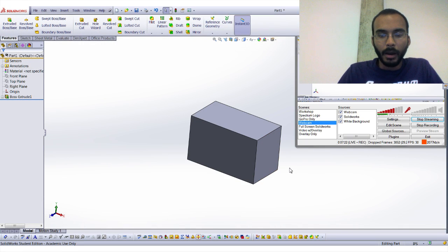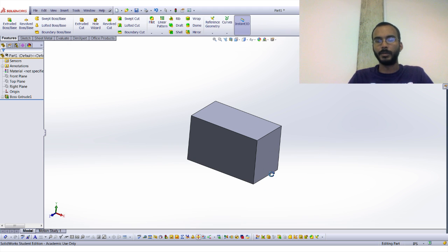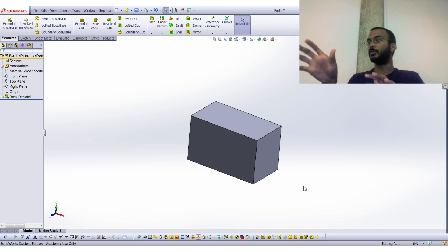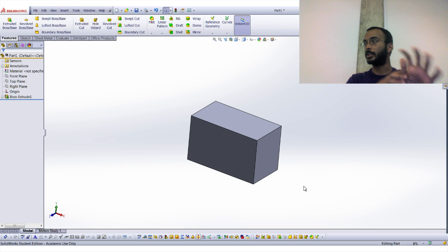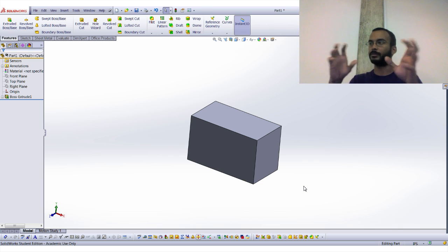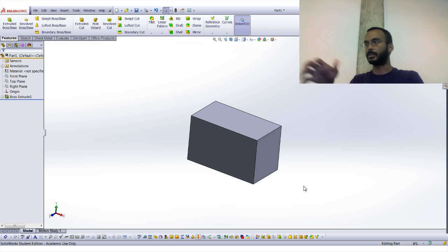Cool. Okay, so this is the first 3-dimensional part. Basically that same process of going into a sketch, drawing something, and then doing some other feature on it is pretty much the workflow that you do for most everything in SolidWorks. There's a lot of advanced stuff, but for the most part, you make a sketch, you do some sort of feature on it, either an extrude or a cut, or there's revolves, there's all sorts of different things you can manipulate it with. But that same idea, basically sketching, drawing out a shape, and then going in and actually extruding it and doing some feature task on it.